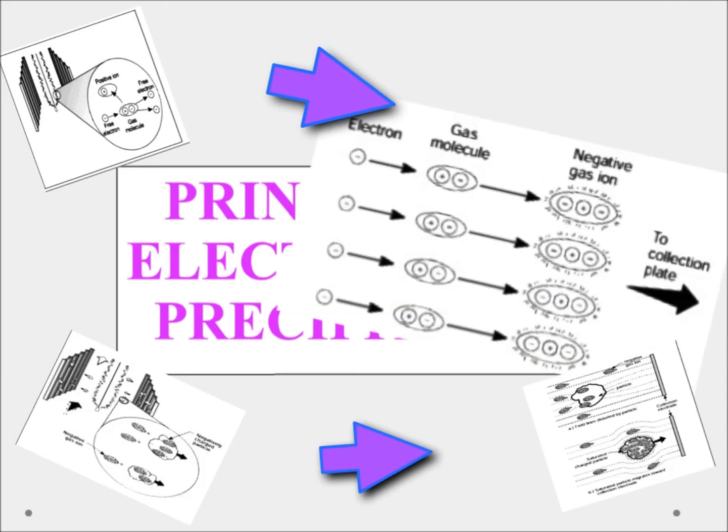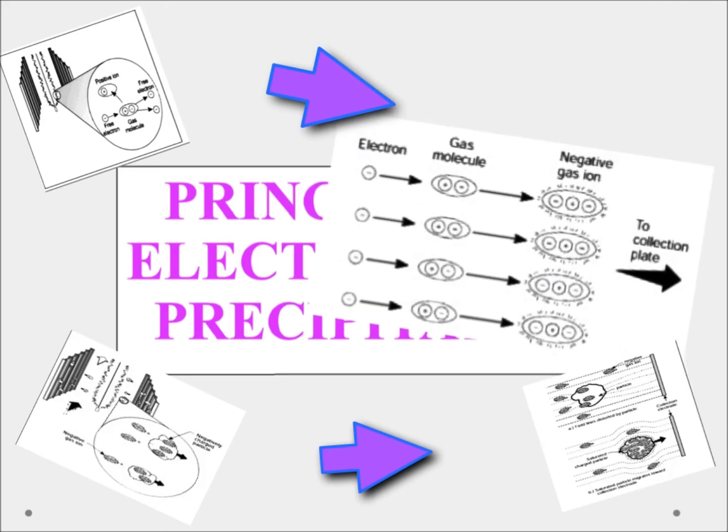During stage 2, the electrons leave the strong electrical field area around the discharge electrode. They start slowing down. These free electrons again strike the gas molecules, but this time they are captured by gas molecules and become negatively charged ions. As the gas molecules are negatively ionized, they move towards the positive electrode, which is also named the collector electrode.